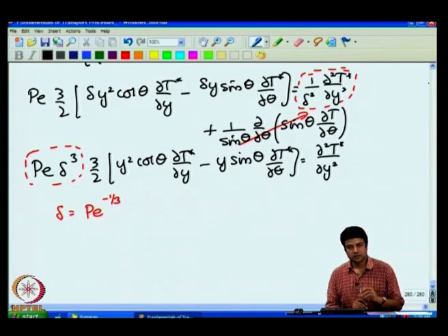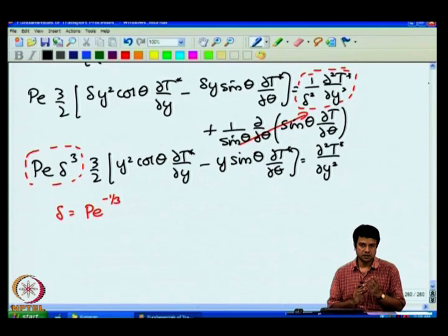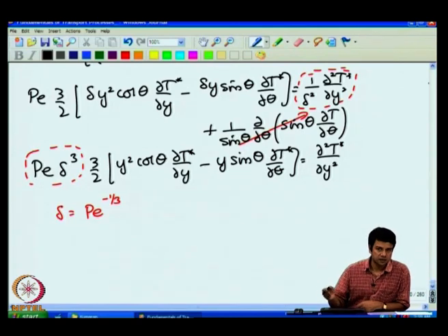Very close to the surface, if we can approximate the velocity profile as a linear function away from the surface, then the velocity increases proportional to the cross stream distance. The diffusion coefficient goes as 1 over that length scale squared. So, ultimately I will get Pe times L cubed being order 1. Okay. So, in that sense it is no longer a surprise.